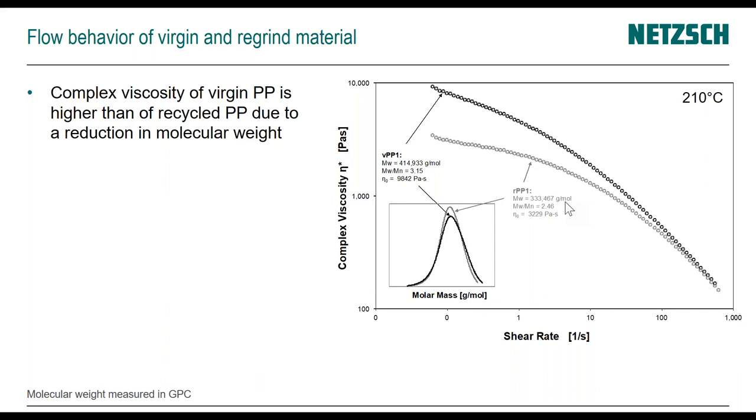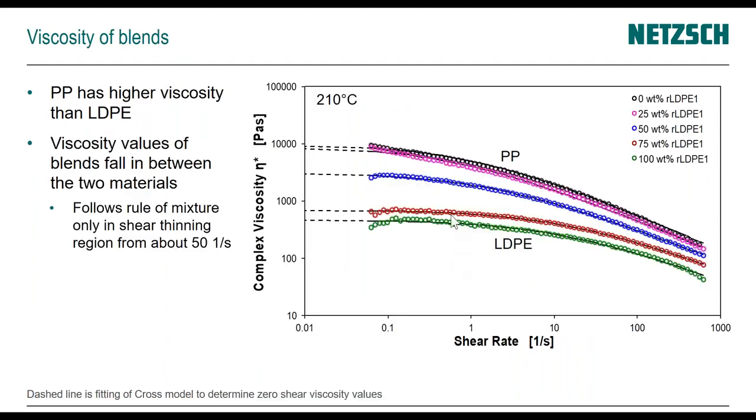So just from that we can learn something about that rheological behavior tells us about the molecular weight, but in the end, for processing, we really want to know how the flow behavior is affected. And that's why, in my opinion, it's very practical to determine the rheological properties and get additional information about the molecular weight distribution.